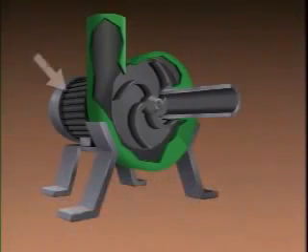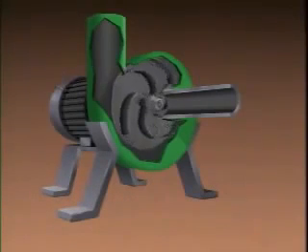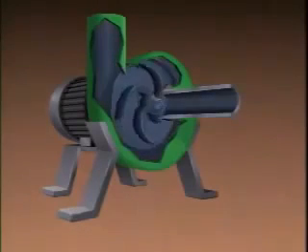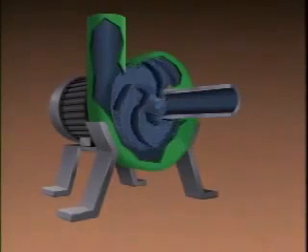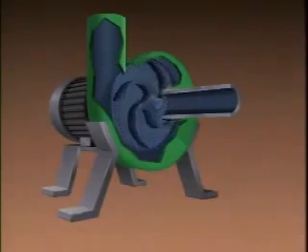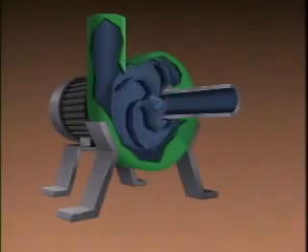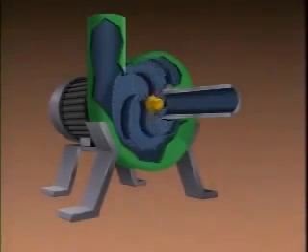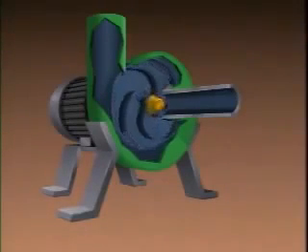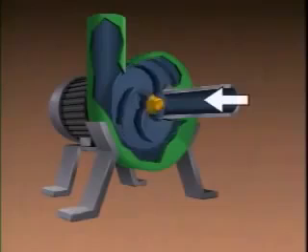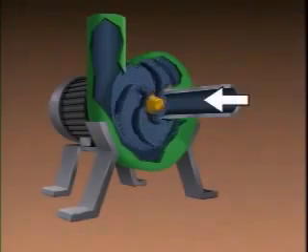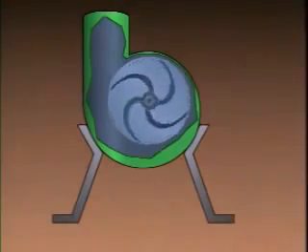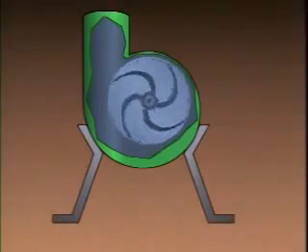During operation, a driver rotates the impeller, creating a centrifugal force that throws the process liquid outward into the volute. The outward movement of the liquid causes two things to happen. First, it creates a reduced pressure area at the suction eye of the impeller. This area of lower pressure draws more liquid into the pump and provides a constant flow of liquid. Second, it causes the liquid to gain speed.